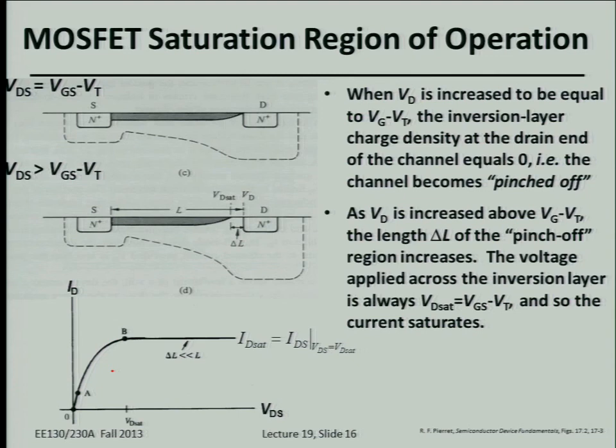Okay, so one very common point of confusion is coming up right here. What happens if you increase the drain to source voltage to be significant? Remember, as I mentioned, the potential in the channel at the drain end is equal to VD, right? But now, what if VD becomes so high that basically the difference between VG and VD is less than the threshold voltage?